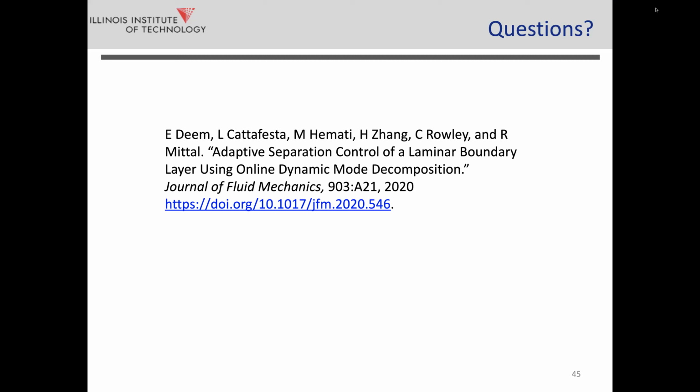That's very interesting, because it seems there is actually a scale of the flow which is much more difficult to suppress. And also, if you go to three-dimensional flows, you mentioned this, that's another interesting application, because now pressure, which is really measuring sort of an overall global response, is probably no longer, this is again a hypothesis, probably no longer sufficient. You may have to make measurements of shear stress in this particular case. And I think that's another interesting problem to look at as well.